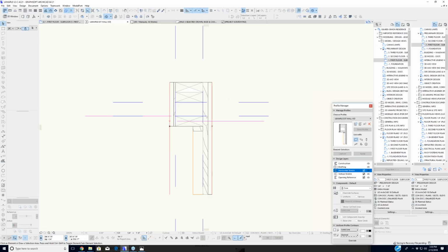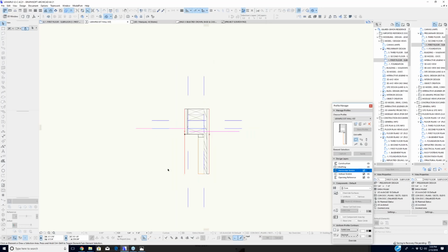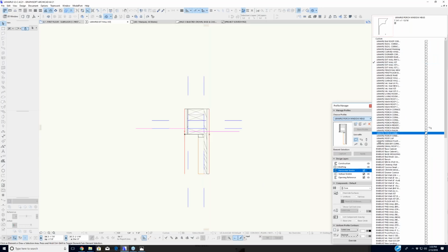Now, during demolition, a lot of things became apparent to the eye. Oh, now I see why that was so thick. They built that entire ceiling down to avoid a cast iron toilet from the second floor. So a lot of things became apparent after demolition. But primarily, this project, and I would say any project, you spend the time on a renovation surveying what's there, photographing it, interior, exterior, really organized folders for photos, and then start creating your cross cuts of where you want your profiles.